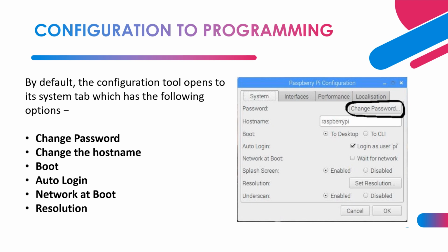Following are the steps to configure the Bluetooth device. First, make your device discoverable for pairing. Now you need to click on the Bluetooth menu at the top right of the screen. It is aligned with the Wi-Fi button. Now choose the Add Device option. The Raspberry Pi will start searching for the device and when it finds your device, click it and click the Pair button.